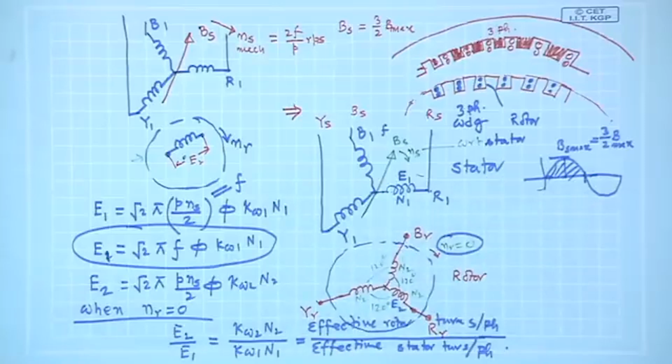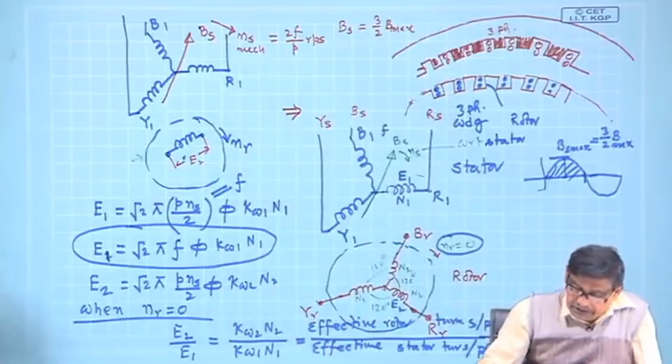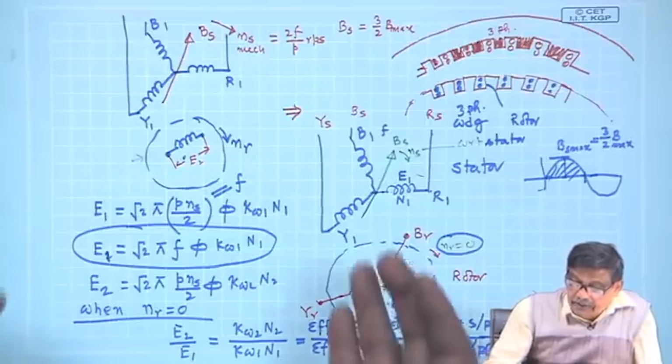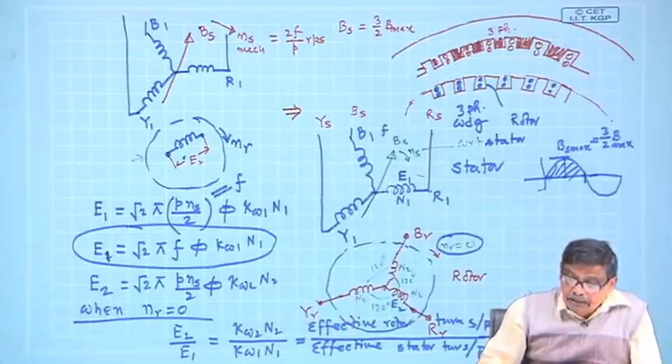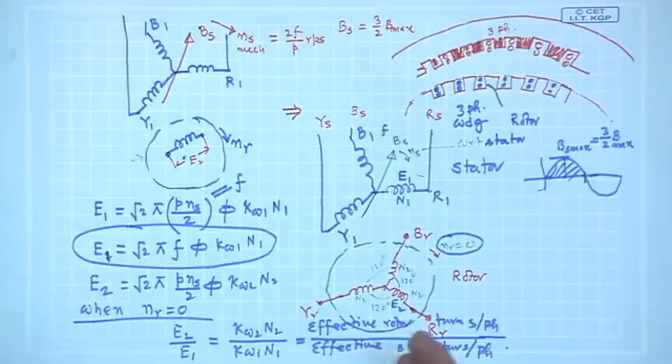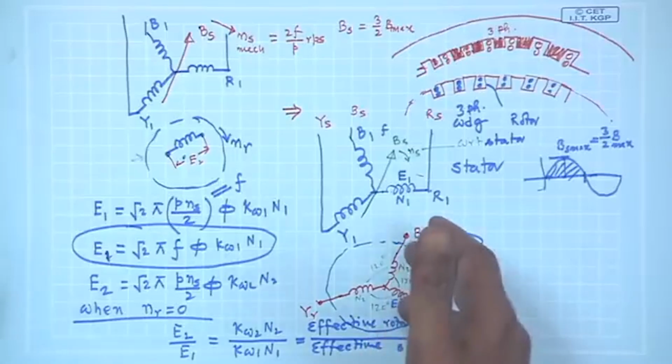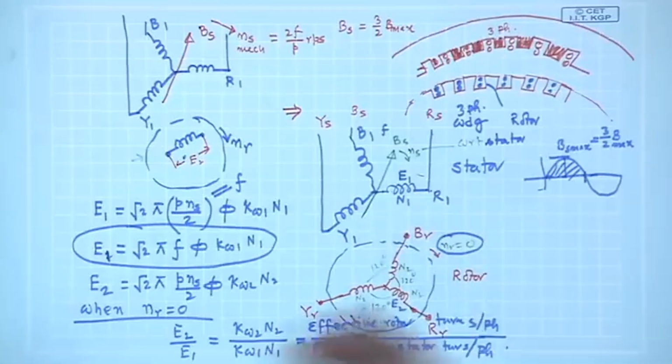F. So, it is almost like a transformer. Why almost? It is a transformer. It looks like you can step up or step down the voltages having same frequency. But the only problem is I do not know yet what is going to happen if the secondary winding also starts carrying current, whether it will remain same in its operation like a transformer or it may differ.